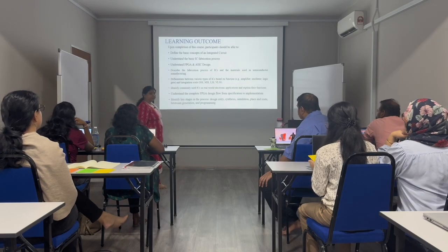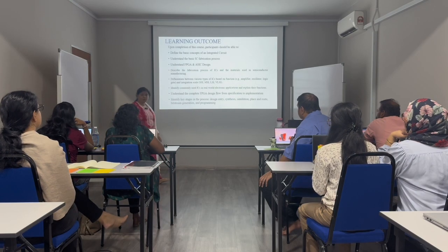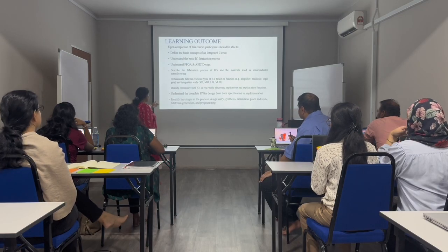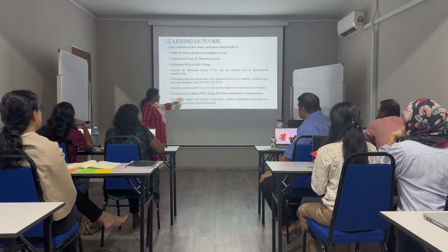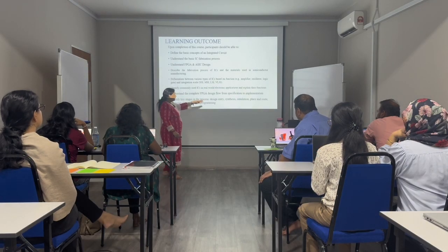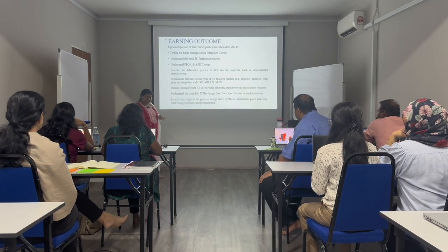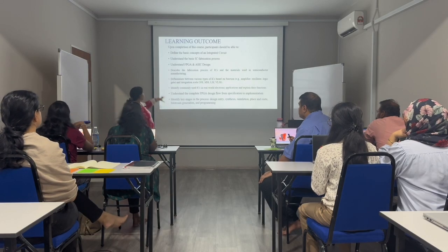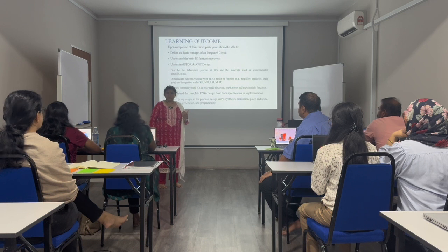And you understand the complete FPGA design flow from specification to implementation, which includes the key stages of the process: design entry, synthesis, simulation, place and route, bit stream generation, and programming. So this is the learning outcome of this presentation.